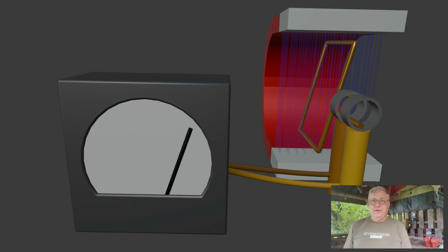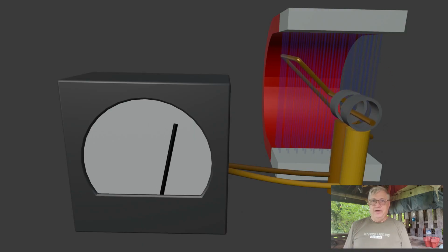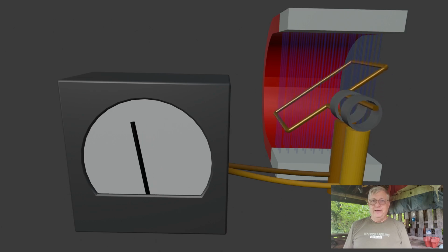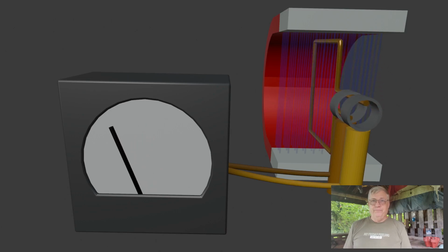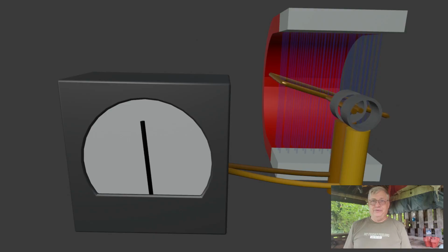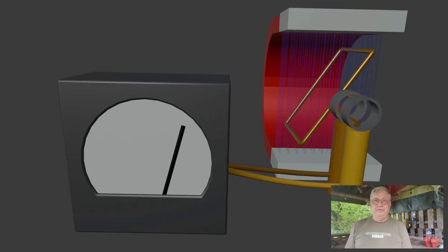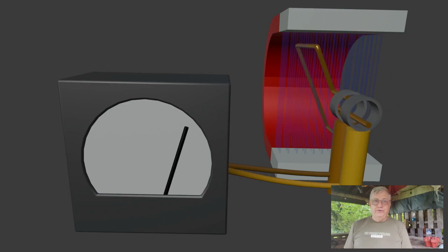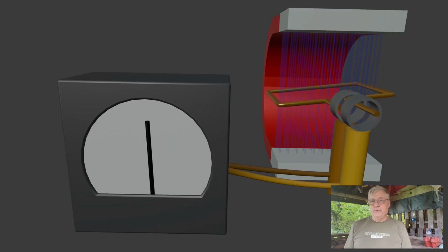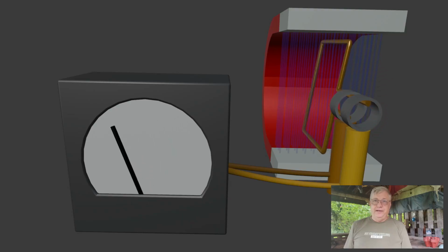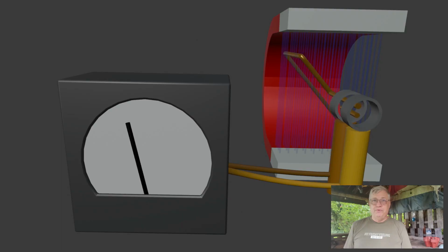Once we reach the top of the arc and start swinging down, the voltage drops off again, back to zero when we hit the horizontal. Now as we're swinging in the opposite direction, same rotation but the opposite end of the magnet, the electromotive force generated is opposite, and voltage and current will be opposite of what we generated before.